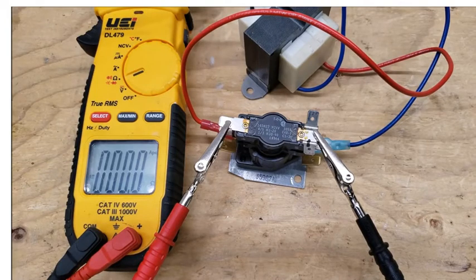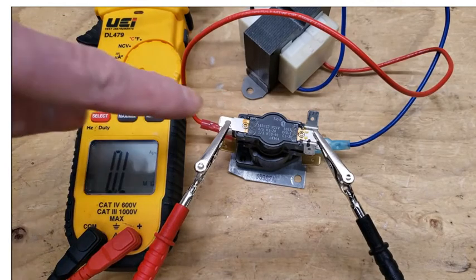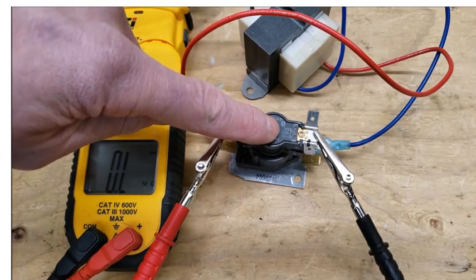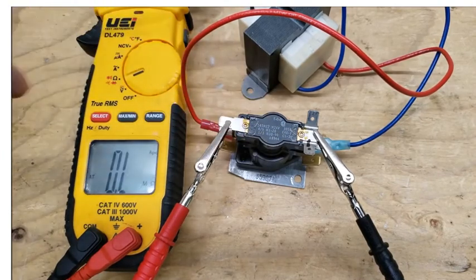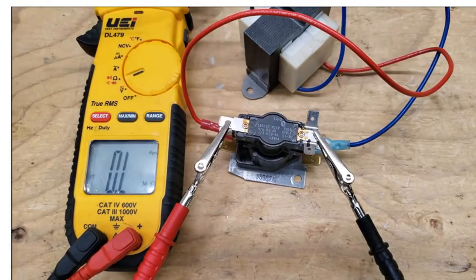And now let's go ahead and see how long it takes for the contacts to open back up again. We've disconnected the power now. There you go. That was on the lower end of the 40 to 120 seconds. So that was probably right around 35 seconds or so. But you see that we are no longer connected on those contacts between 4 and 5.